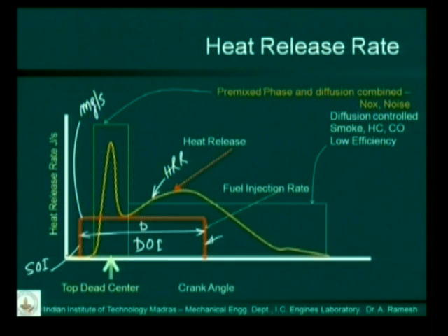So combustion, the injection starts and lasts for some time. This duration of injection could be something like in a normal diesel engine. I'm not talking about an electronically controlled diesel engine. It could be something like 30 degrees or so of crank rotation, which can translate to something like between 1 and 2 milliseconds.